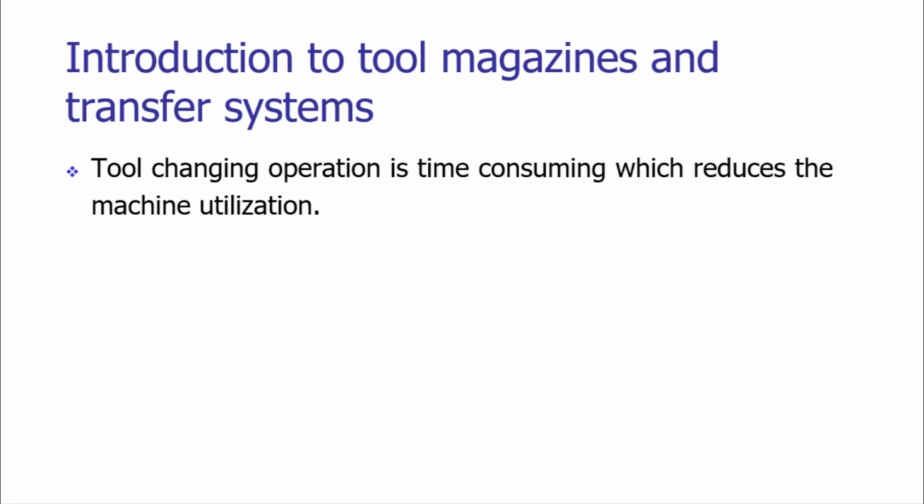When we are working with very hard material, high strain material, the possibility of tool wear is very high. The tool is wearing off very quickly. Thus, more frequent tool changing operations need to be carried out. So these are affecting the productivity.